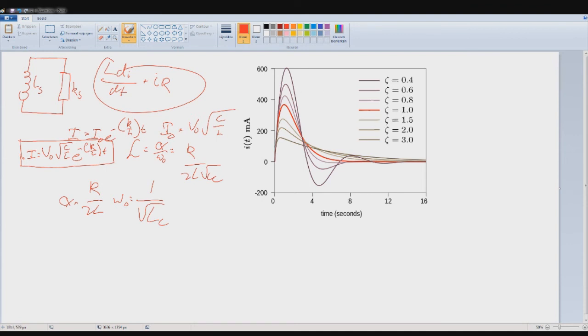And you can see here oscillations, and it's becoming less resonant. Well, it becomes more damped, enters critically damped. I think that's 1. Yes, that's 1. This is critically damped, where it just follows this function.